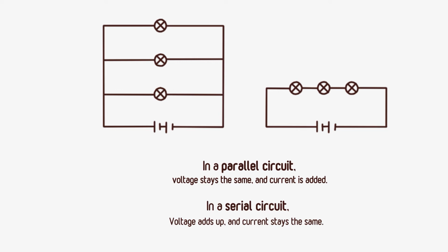The pro of doing a serial circuit is that you can use a lot less wires. Specifically, when you talk about solar panels, what happens when this middle part has shading, where you don't get sunlight through, electricity can't travel through it. So the downside of it is you slow down your whole system. And again, your voltage is a lot higher.